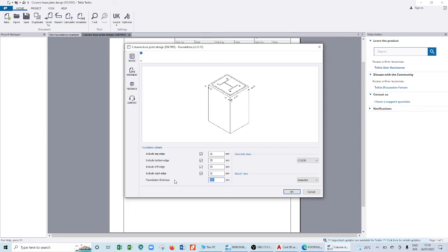Remember, if I just push in the anchor bolt something like 100 into it, it will not be holding. At one point, it can break off if there is a pulling force. So me, I'm going to start mine with maybe let's say 500 depth in the concrete. Then after that, you say okay.